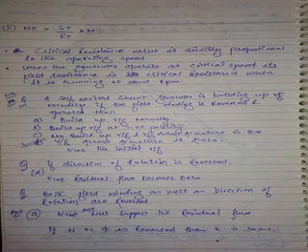But here, now listen: the field winding is not reversed, the direction of rotation is reversed. That's why when the current flows like this, the residual flux has been erased away. Now imagine the direction of rotation as well as the field winding both reversed. Means F comes here, FF goes there. So like in the previous case, current is flowing from F to FF. Here also current is flowing from F to FF.